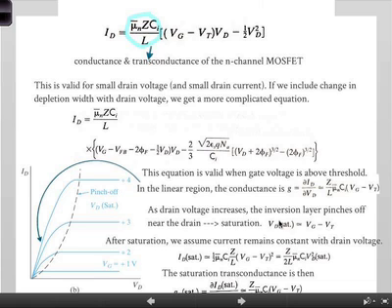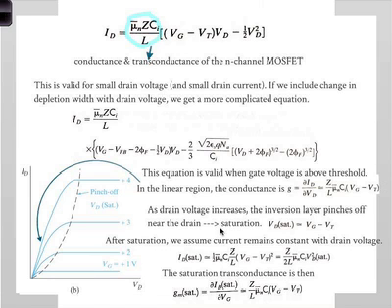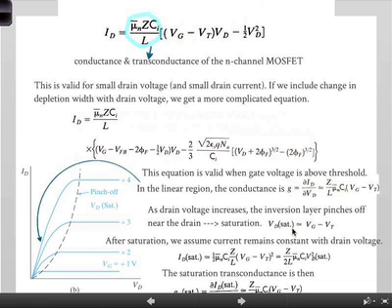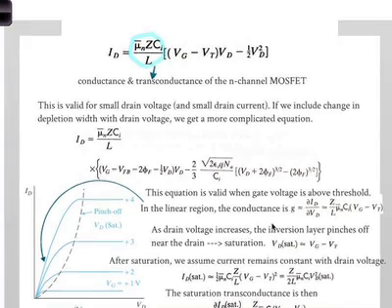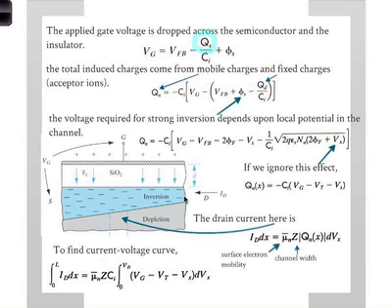As the drain voltage increases, the inversion layer pinches off near the drain, like we said, and you get saturation. The drain voltage where the saturation occurs is when, if you look at this picture, remember the voltage here is coming down. At some point, the voltage from the gate to the body here will be just at the threshold, which means that the inversion barely exists.